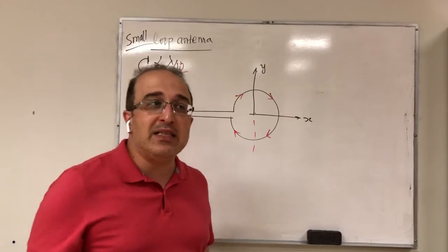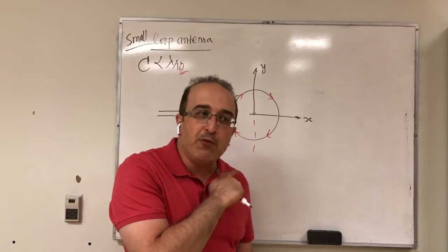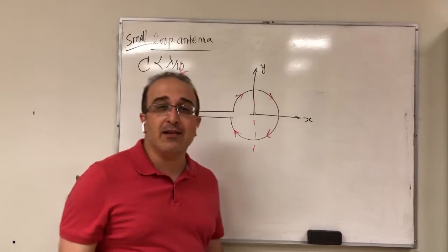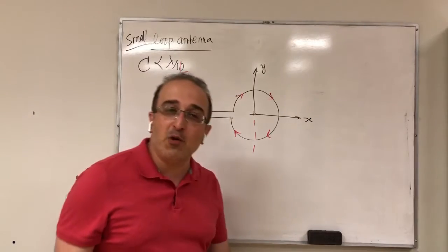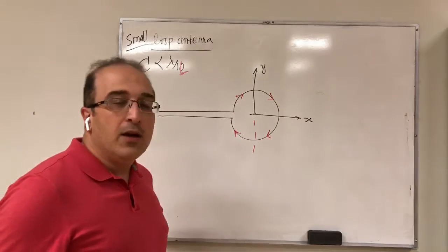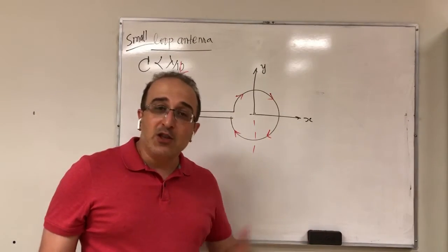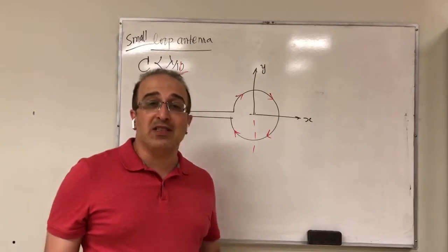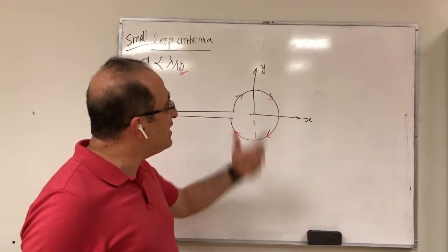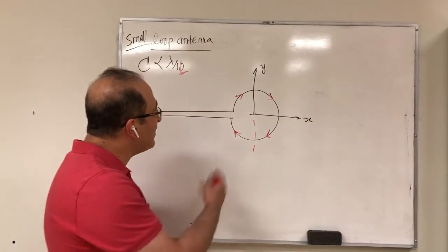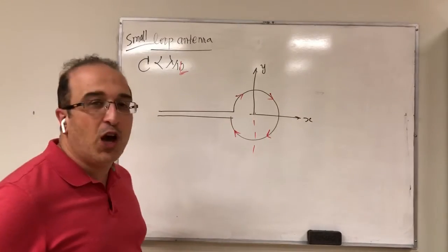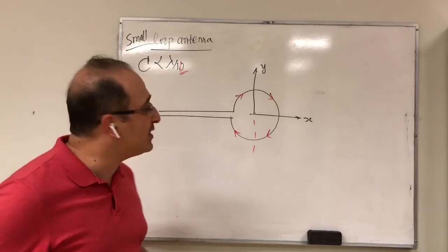So here you could be mistaken because I've shown you that the 1 lambda circumference had maximum radiation in this direction. You might say, okay, this is going to have maximum radiation on the z-axis, which is toward you. But that's not true. That's not correct. In fact, this is exactly opposite. The 1 lambda loop has maximum radiation here because you've seen it as 2 dipoles. But even if you think of this as 2 dipoles, these 2 dipoles tend to cancel the effect of each other.